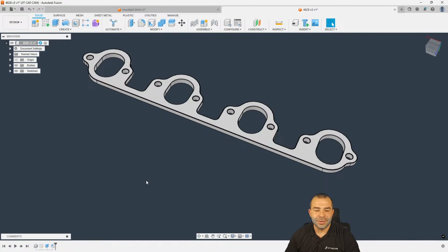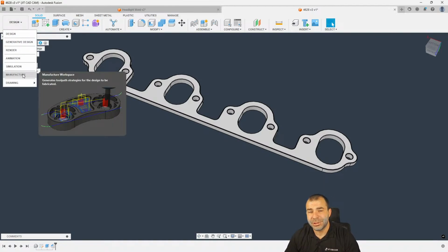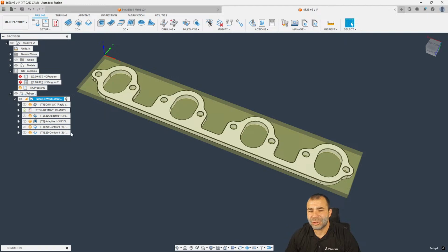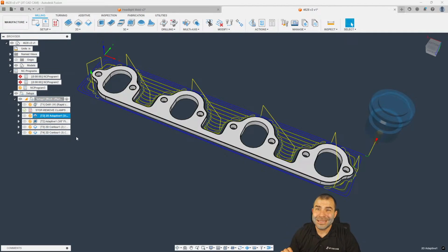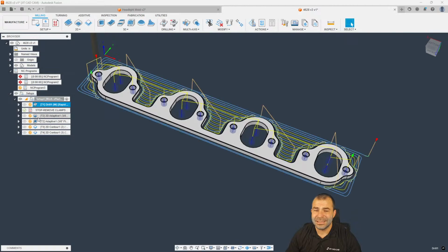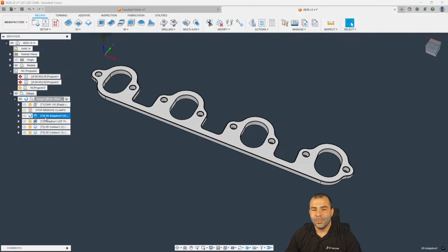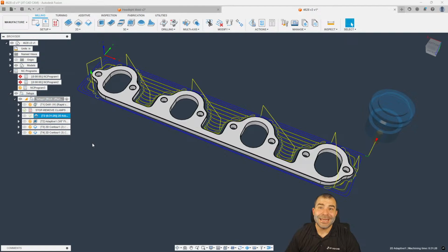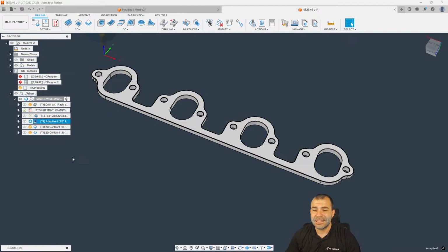And the real power of this just multiplies, because now I think you all see the big picture here, where under manufacture, remember how we did silhouette? What I'm doing here is I can easily take any one of my toolpaths and regenerate them. And what that will automatically do again is go out and see outside silhouette, inside silhouette.